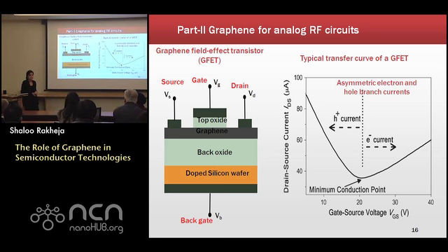So at the end, why is the delay only... No, so over here, it depends actually. I really see your point. But over here, what we're doing is assuming that the graphene is deposited on a very good substrate like boron nitride that has a very high mean free path of 300 nanometers. And even for the mode bottleneck issues that I'm talking about, the contacts, we're assuming a transmission coefficient of about 30%.